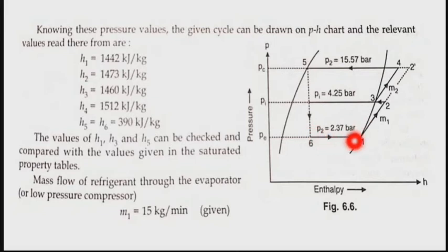The first point starts in the dry region. A quantity M1 flows through the first compressor and reaches the second point, and then reaches the third point. The pressure is the same, but the enthalpy decreases, and it reaches point 3. Then the mass flow rate M2 flows through 3 to 4.